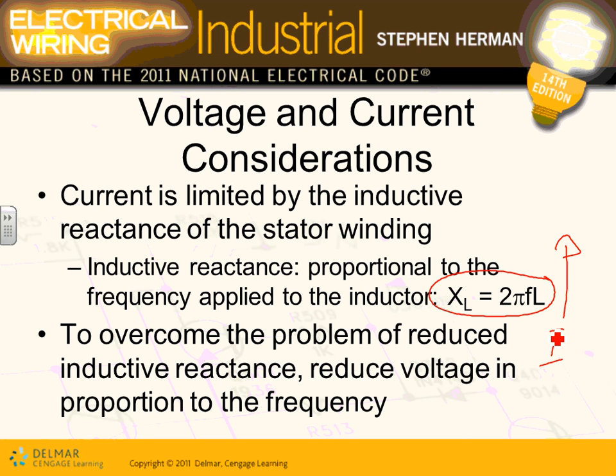So the smart engineers said, hey, here's my frequency. I will reduce the frequency and, at the same time, reduce the voltage. By reducing the frequency, guys, and proportionally reducing the voltage, they can control the speed of an AC motor without burning it. Welcome to the VFD. So what does the VFD do for a living? It reduces the voltage and the frequency of a motor to speed control it.